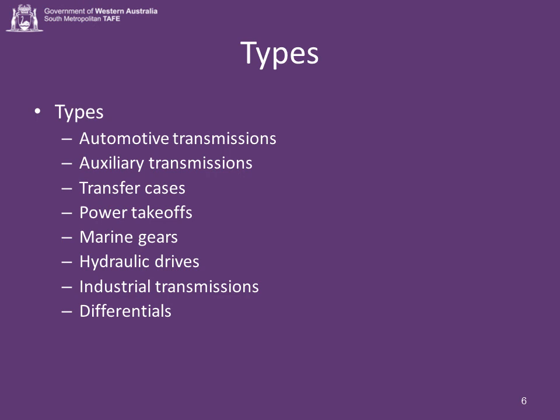Less well known than the first, this technique solves industrial problems when the superimposition of one motion relative to another is required, such as timing of cutoff, registration control on printing presses, tension control, and phase shifting on textile industry equipment.